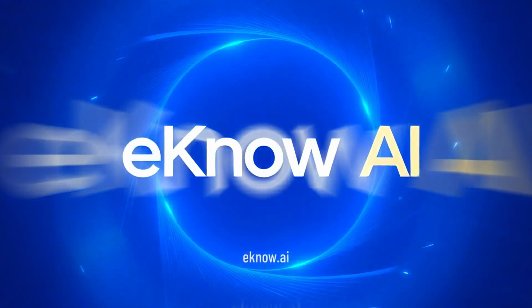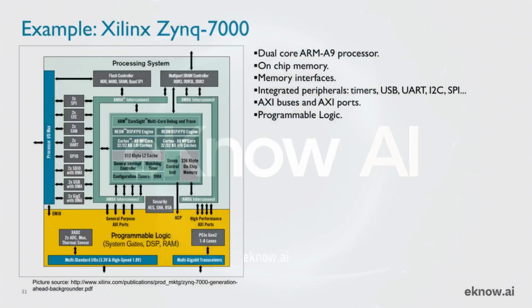This Xilinx ZYNQ 7000 is a fantastic, real-world example of the programmable SoC, or PSoC, architecture we just looked at. It beautifully illustrates the concept of combining a standard processor system with flexible, programmable hardware on a single chip. Let's break down this diagram. You can see it's divided into two main sections: the processing system, or PS, and the programmable logic, or PL.